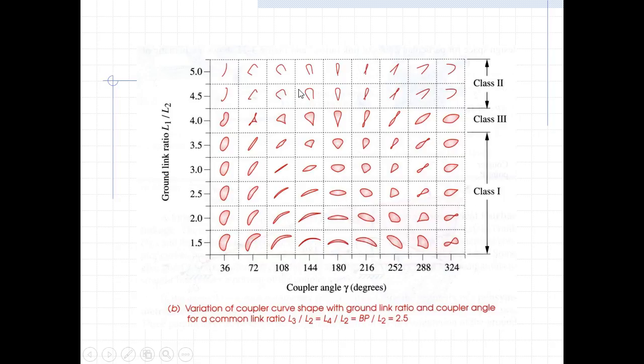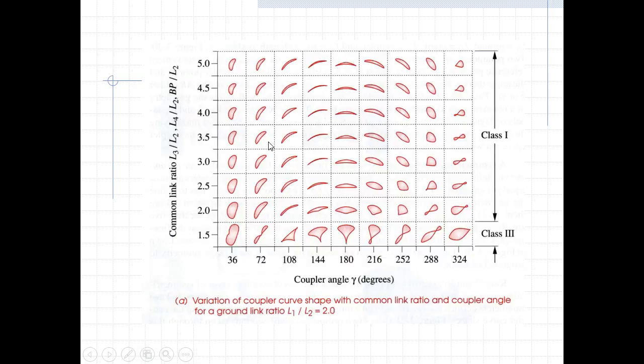are not Grashof. And so you see here that these coupler curves do not come back and connect like all the others do, because there's a certain point where we have to stop and move our crank in the opposite direction because they are not Grashof. The axis of symmetry again is O2O4, when the crank and ground are collinear extended, as previously shown. We need 5 parameters to define a non-symmetrical 4-bar linkage. Okay, so if we're talking about a 4-bar linkage that's non-symmetrical, we need 3 link lengths and the length and angle to the coupler point.